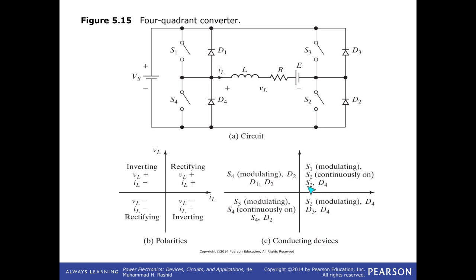And S2 and D4 are operating. So when the switch S1 is on, current is flowing like this, and then if you put it off, current is going to flow through that one. Then when you put it on, current is going to flow like that. So from source you send the current is rising, and current is then dropping, and we already know the maximum and minimum current, and we already know the time domain equations. It's the first quadrant operation.